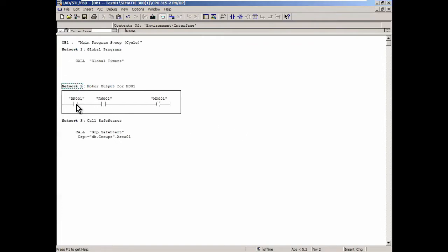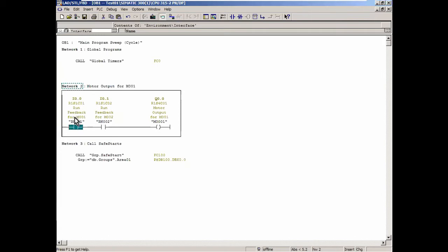If I now move across, you'll see that I/O now has rack 1, slot 1 in it. If I put the symbols on, you can see there's a whole comment of what that shows you: rack 1, slot 1, channel 1, rack 1, slot 1, channel 2. Now notice I made it ones, not zeros, because when you're counting, you say first channel, second channel, not zeroth channel. I know in binary we all think binary, but some technicians, when they're looking at the PLC, just say it's the first channel. They don't think of addressing. So anyway, that's just a minor thing.